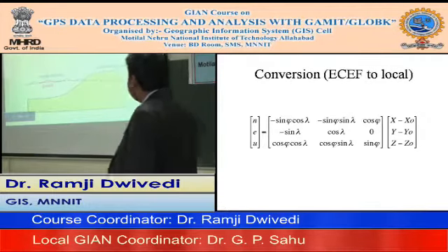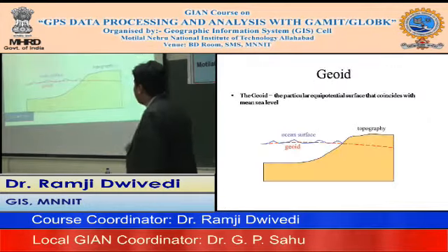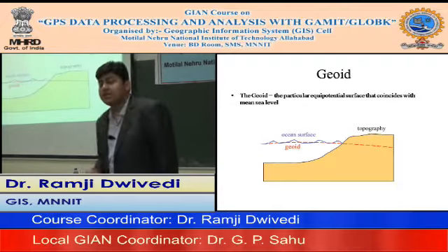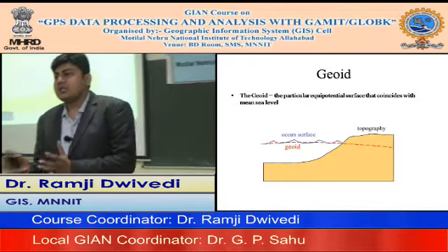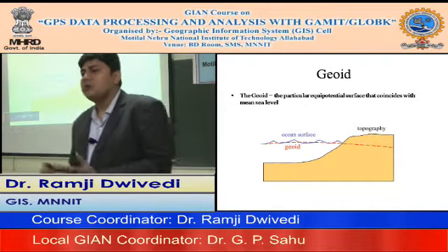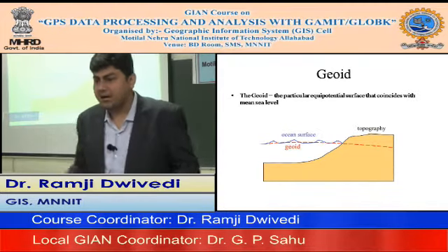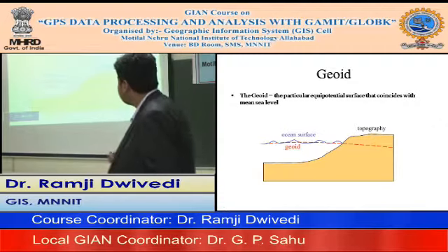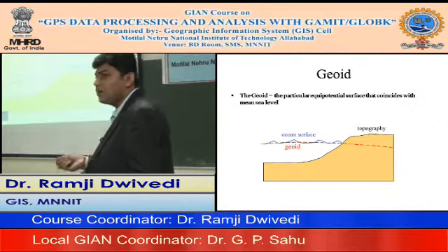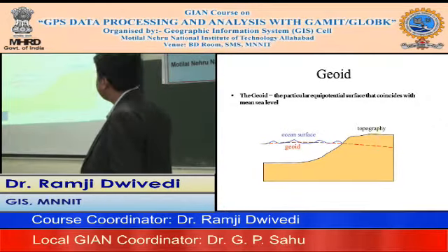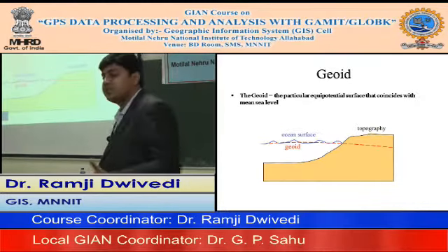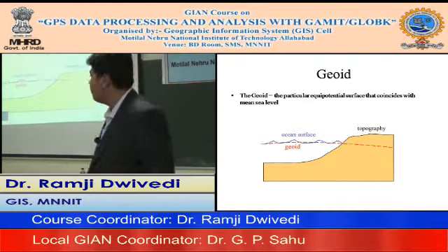Similarly, we understood the mean sea level as the equipotential surface, because people are more interested in finding the height with respect to their local datum, which they have defined for their purpose, because of the fluctuation of the geoid according to the continent. The mean sea level is defined as a particular equipotential surface, call it the local geoid.